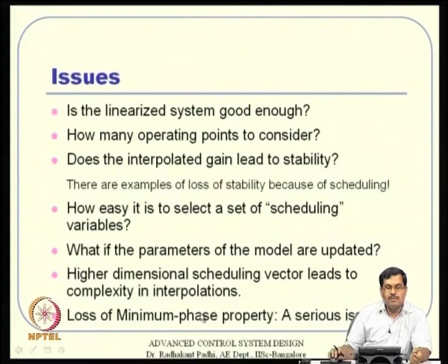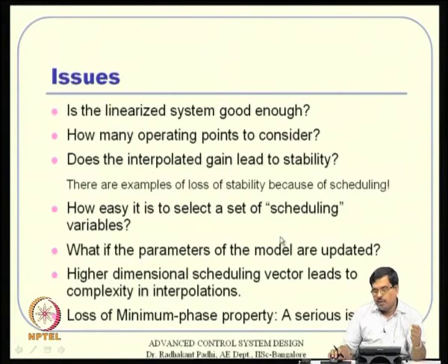Those kinds of situations are not very nice, and even if tracking is good, non-minimum phase systems will have a reverse response in the beginning, and this reverse response is very bad for the pilot because it will lose handling quality properties. The pilot will feel that the system is not behaving the way he wants it to behave. So, there are many issues because of which gain scheduling is not a universal design. We certainly need better approaches to give better design tools for the engineers.